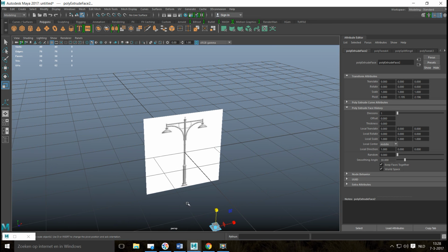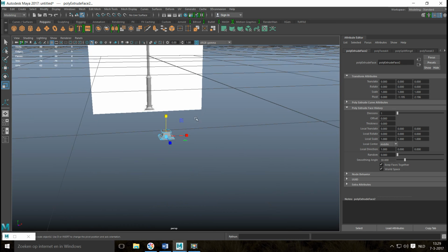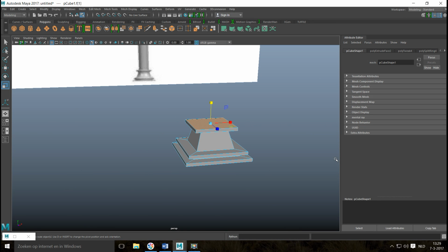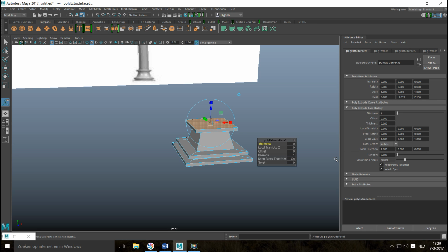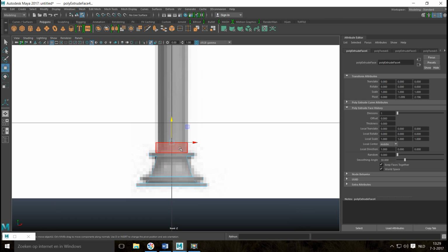Just hang on one sec while I turn that thing off so we don't get all these messages. Yeah, there we go. So we got that. That's a good basis. Then we're going to right click on the face. There we are. We're going to hit Control E to extrude, R to scale in. Let's bring that in a little bit. And then hit G to repeat last command and W to pull up, like so.